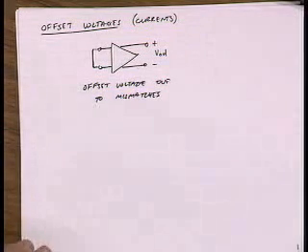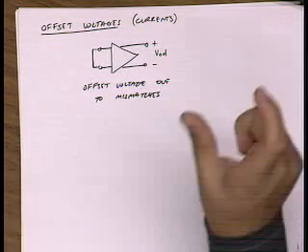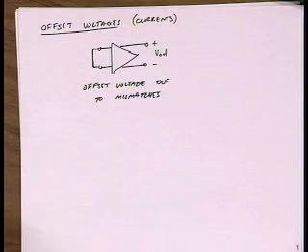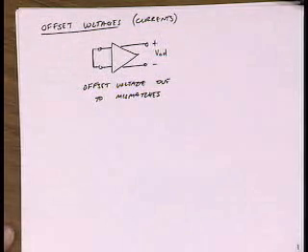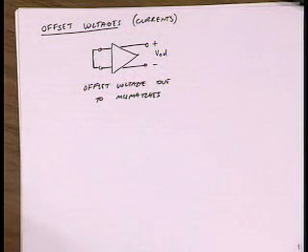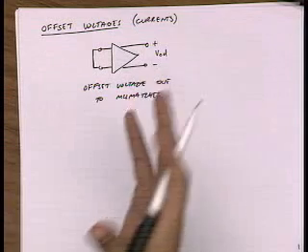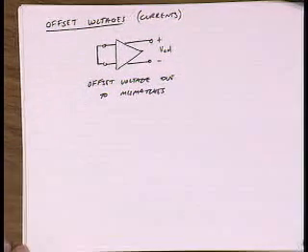We know that when we build an amplifier, if it's perfectly symmetric, then if we put in a 0 input voltage, we get 0 output voltage. But if there's any kind of asymmetry in the amplifier, two resistors that are supposed to match don't match, or currents in two branches are supposed to match and they don't, all these things lead to a systematic offset voltage. I say systematic because I want to distinguish it from noise that's varying all the time. Of course, if you build 10 amplifiers, they're all going to have different offset voltages, because of the mismatch. One resistor is going to be too big in one case, and in the other case too small, so it's going to vary all over the place.